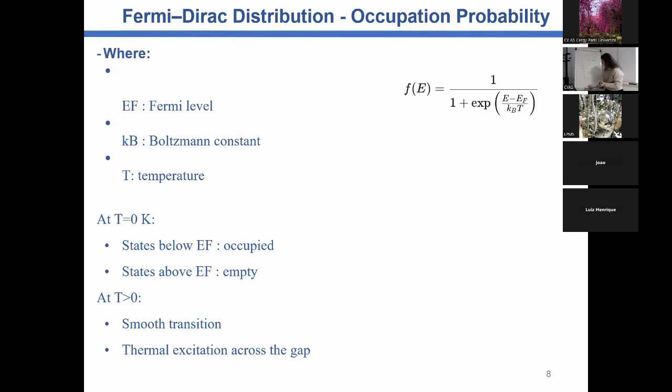What I mean is that the N-type will be aligned with the Fermi energy, so it will create a Schottky barrier here that will allow the movement on this side but will block the movement on this side.